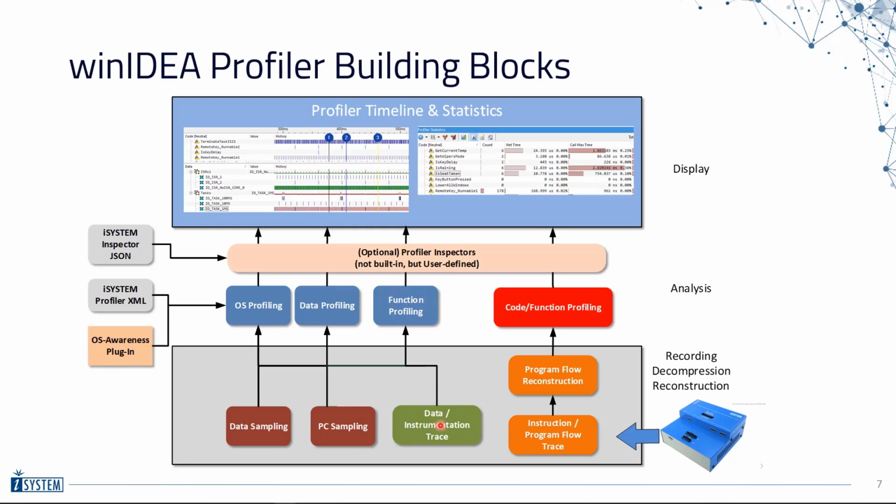Or the data is written by the OS scheduler and tells the profiler which OS task is currently running. This is typically the approach for tracing the running task of an AUTOSAR OS based on the so-called ORT file. Or there is no further interpretation needed at all, so plain data profiling is done.